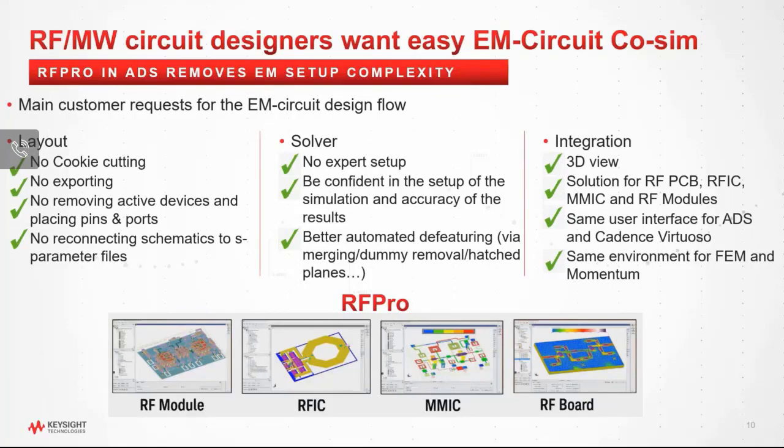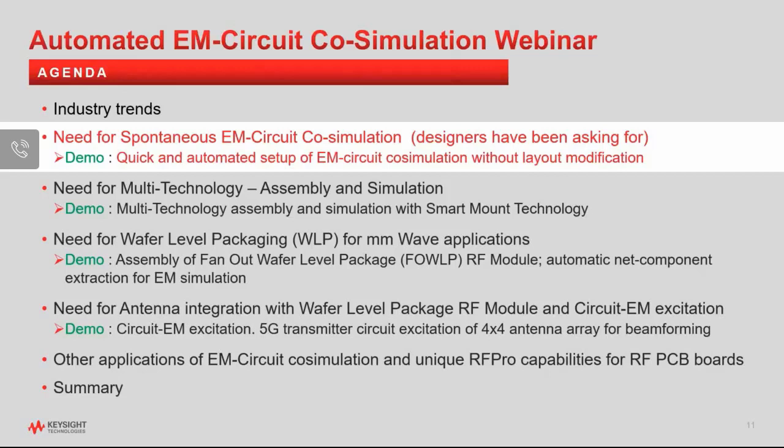1, no layout modification or cookie cutting to do an EM analysis. 2, automatic and correct setup of EM analysis to produce results that can be trusted with confidence. And 3, tight integration with circuit simulators in ADS and Cadence Virtuoso with the same environment to access the FEM or Momentum EM solvers.